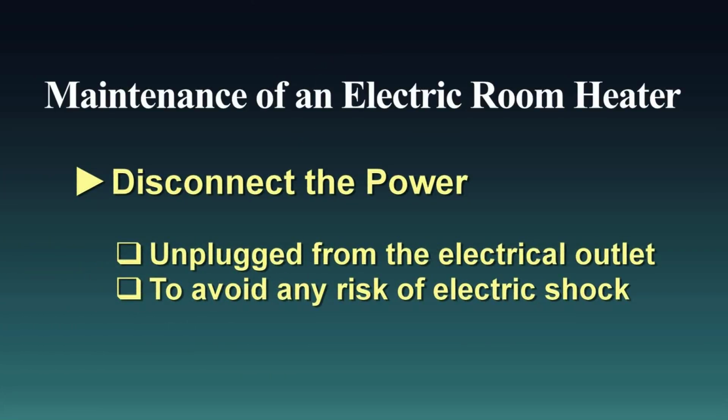Disconnect the power. Before starting any maintenance task, ensure the electric room heater is completely turned off and unplugged from the electrical outlet. This step is essential to avoid any risk of electric shock during the maintenance process.